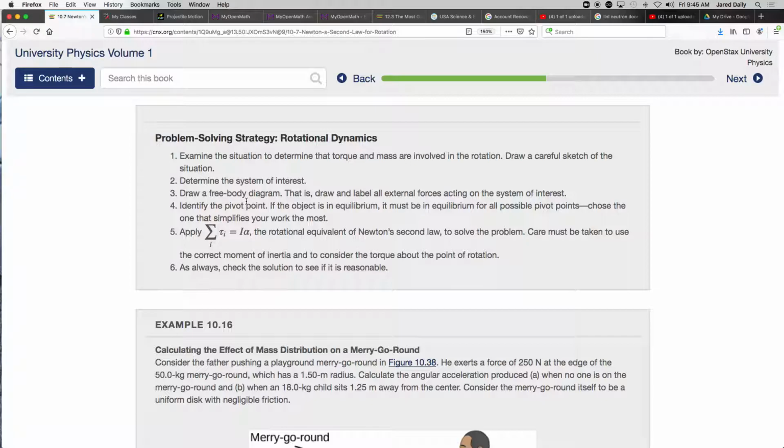Our free body diagram became a point, right? Well, in our case, it's not going to be that. We're going to keep the wagon or something similar to a wagon. So you might turn it into just a rectangle without wheels, and then you have a force. But now we have to say, where's our 0 point going to be? Maybe it'll be here. What's our distance to that force going to be? Because now we're going to have to label forces and R vectors for every force. And there should be an R vector for each force. That R vector should go from your 0 point out to each force.